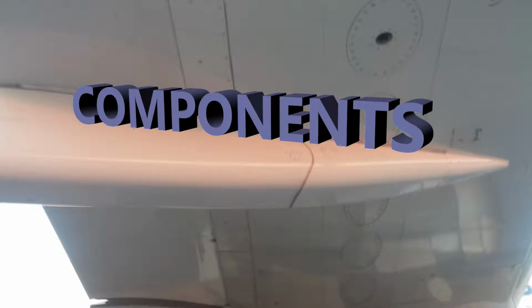Okay. All right, so just a reiteration here: when we talk about the fuel quantity indicating system, what components do we have? What makes up that system? Well, you're going to have a multi-tank indicator, your pre-selector, your condensers, and, I didn't mention this, your onboard replaceable module. Okay, so that's your OBRM, onboard replaceable module, your computer for this system. And of course, remember I mentioned the probes that are located in the tanks.